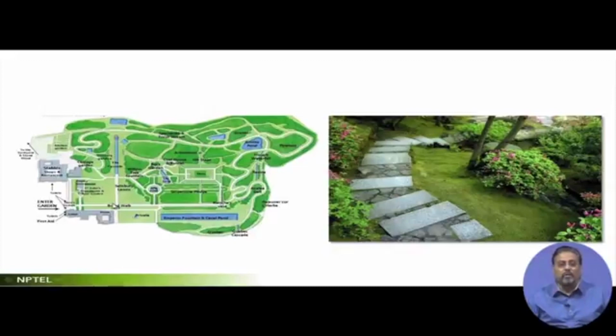So my suggestion is, I always use this as a gospel. When you are planning, do not get impressed by your base plan, how good it looks, how colorful it is and how patterned it is. Always try to judge it by the experience the person is going to have when he sees the whole plan from his standing point, and then the whole thing becomes different. What looked like a green patch over here might be a woodland, which becomes a vertical plane when you are seeing it from here. This is a very, very serious issue in landscape. It is true in urban design as well, but I am focusing on landscape.